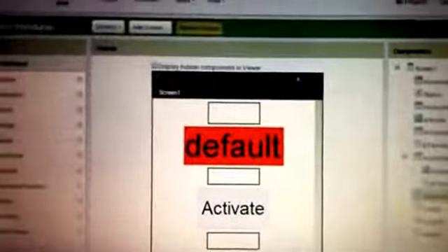In this program, there are some key things that you need to remember when you program your Bluetooth. The trick that I do here is I have my delimiter byte, which I set to 35. 35 in the ASCII table is actually a hash key. Let's see. Yep, this is a hash key, with the decimal 35. I will explain later why I use this in my Arduino code.